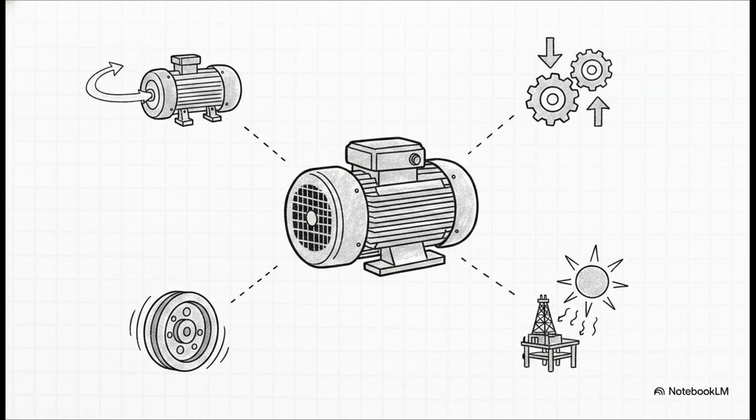First, we need to account for what's called end-of-curve operation on centrifugal machines. Second, over the lifespan of the equipment, things just get old, so we have to accommodate for drops in efficiency. Third, that motor needs enough surplus torque to literally get a heavy load spinning from a dead stop without overheating. And finally, extreme ambient temperatures offshore can seriously degrade performance, so this margin provides a vital buffer against the heat.